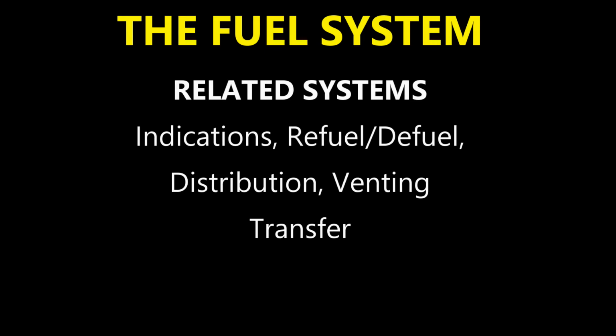So with fuel supply to the engines, we've got the boost pumps. We've got 6 boost pumps located, one for each tank, right? So if we have a failure of one of the tank pumps, then the other pump is automatically supplying the fuel. Okay, so we don't have a problem when it comes to that.